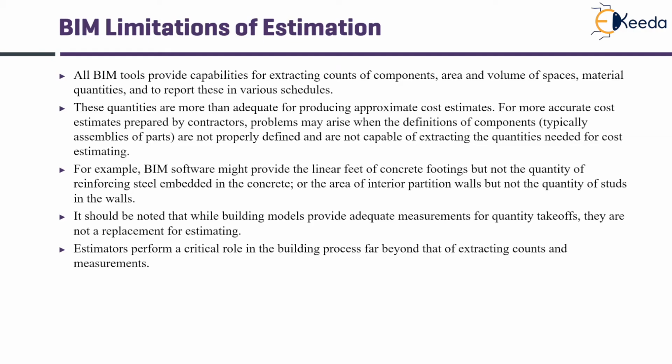For example, BIM software might provide the linear feet of concrete footing but not the quantity of reinforcement steel embedded in the concrete, or the area of interior partition walls and quantity of studs in those walls. Hence, it should be noted that while building models provide adequate measurements for quantity takeoffs, they are not a complete replacement for estimation. Therefore, by introduction of BIM, we should not think that the role of a quantity surveyor or estimator is completely replaced or redundant. Estimators thus perform a crucial role in the building process far beyond the extraction of counts and measurements.